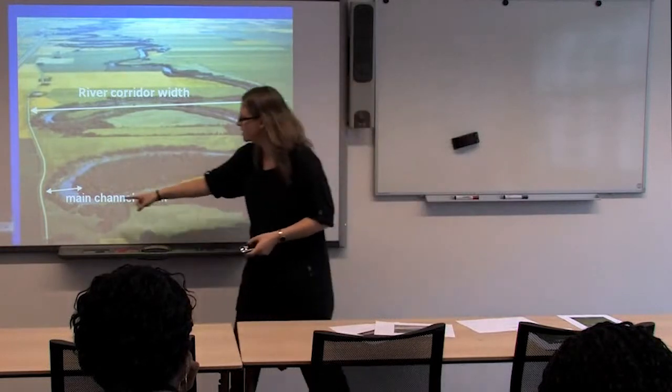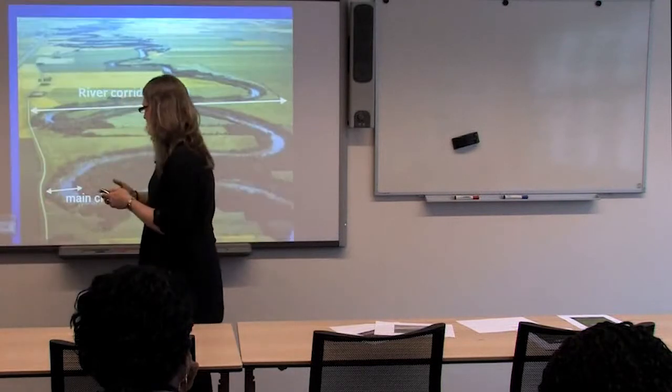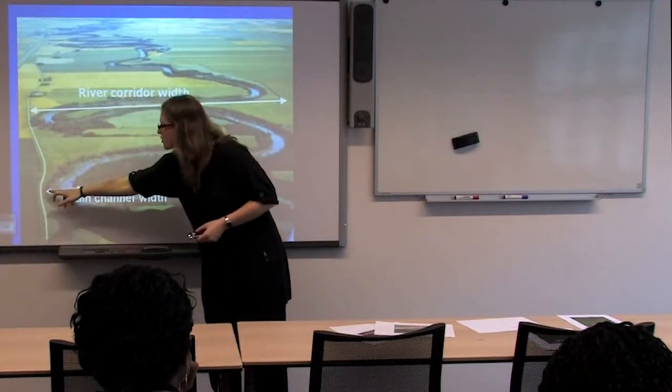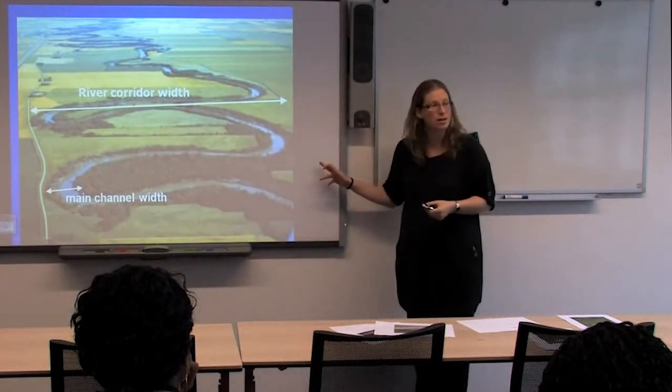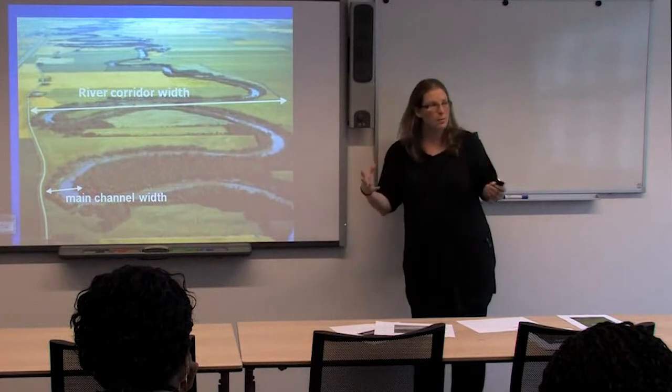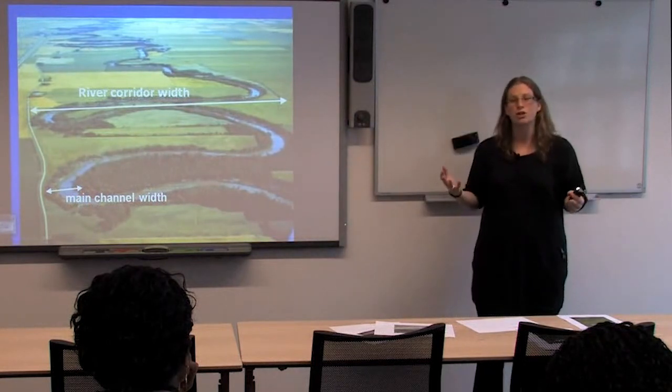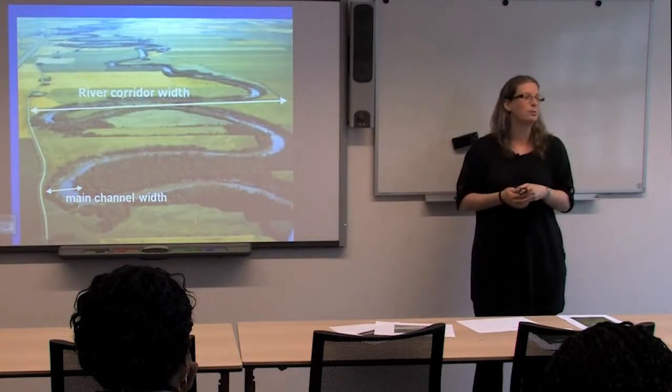So when you're setting out this cross section, you would start your datum here, and you would continue all the way across to the other side of the corridor, so that you pick up that information, the storage available to that river, the floodplain.